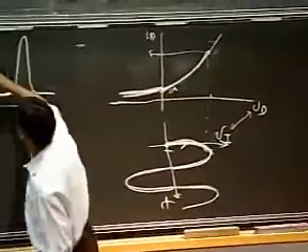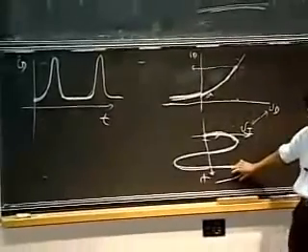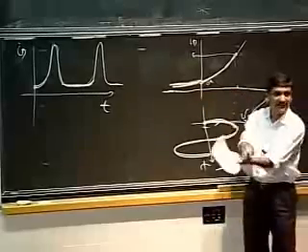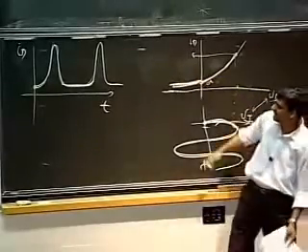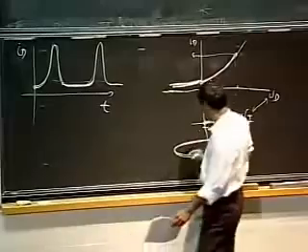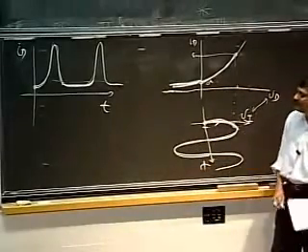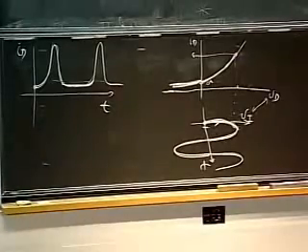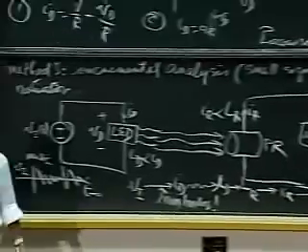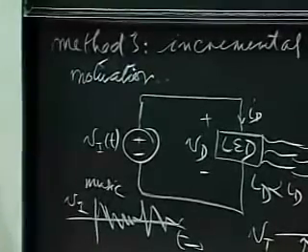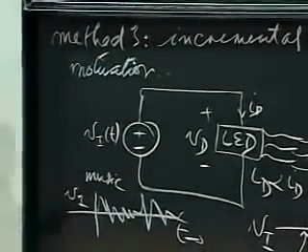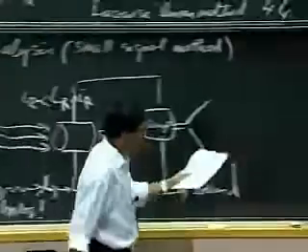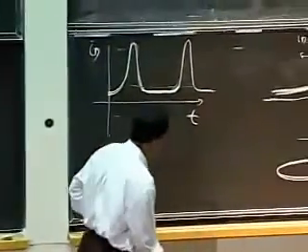So I get high rising peaks corresponding to these two. And for negative going currents, negative going voltages, it simply compresses them to a low positive value here. And that's what I see here corresponding to negative excursions. So what this will do is, if I input sound here, when the sound has negative going excursions, it will simply scrunch them, but will more or less let the positive things through, and that is going to give rise to a bunch of distortion in my signal.